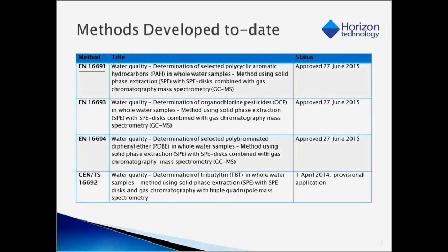Whole water, again, is river water, lake water, underground water, and all kinds of water, or even drinking water. The method to analyze and extract is solid phase extraction with SPE-disk combined with a gas chromatography mass spectrometry, GCMS, system. The other methods that were adopted recently were EN